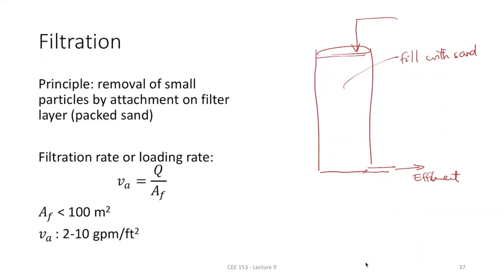Either way, the process is you have sand particles. As the contaminants move, they can stick around here. So this is sand, and biofilm also develops with time. Those biofilms will also capture more organic pollutants as well as small bacteria or pathogens. So why is filtration important?